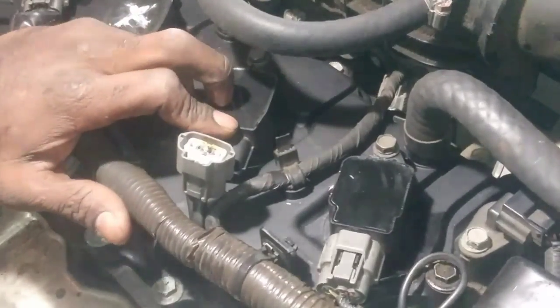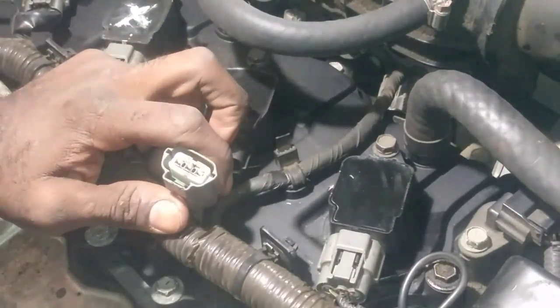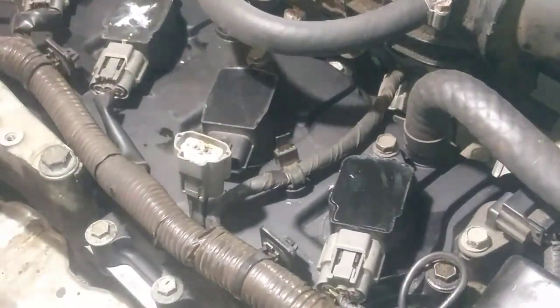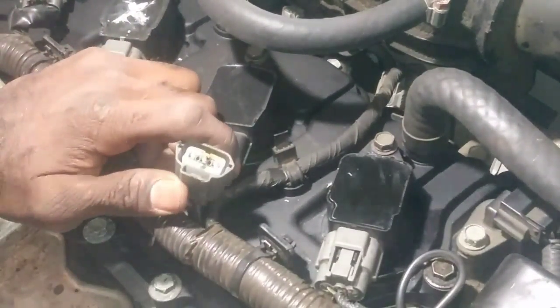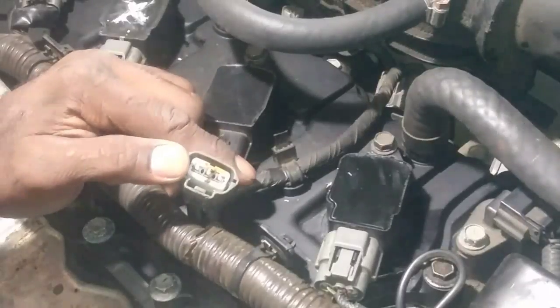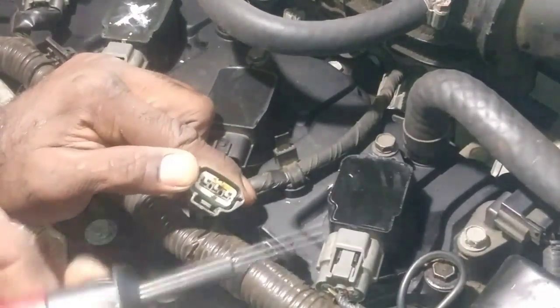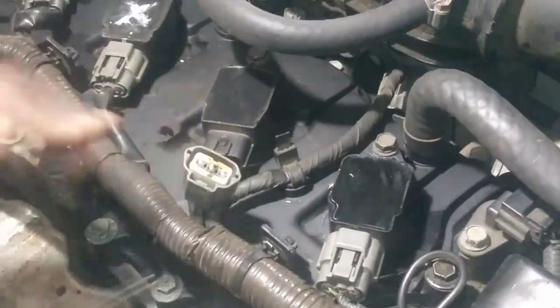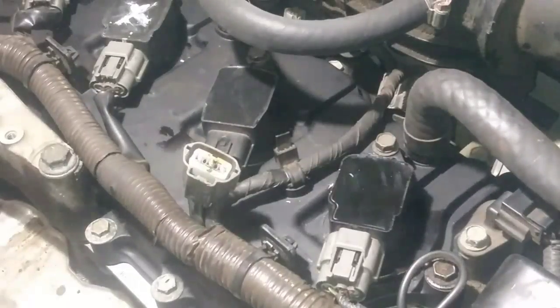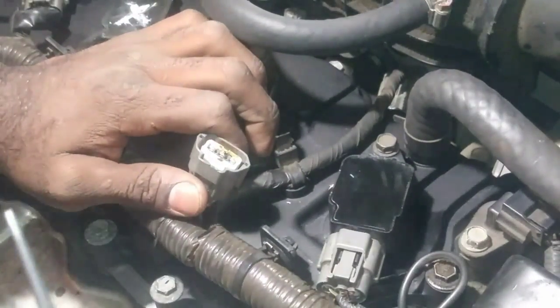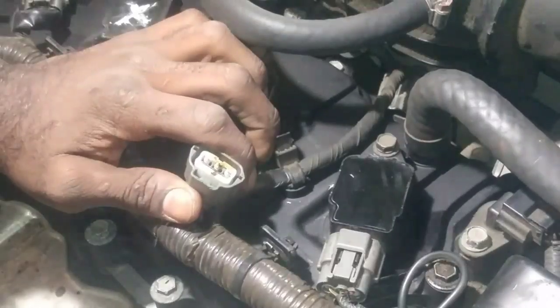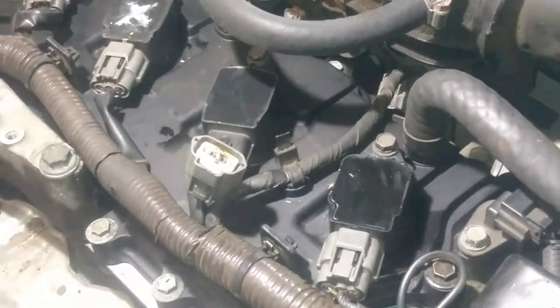Just the basics. You can use a test meter to find out which one's 12 volts and ground, but I like to use a test light simply because you don't want to get any bias voltage and mess something up, especially when that signaling side is typically going to be a low voltage reference, meaning that it's similar to ground. So I'm on ground right now with my alligator clamp. It's on the ground side on the battery.